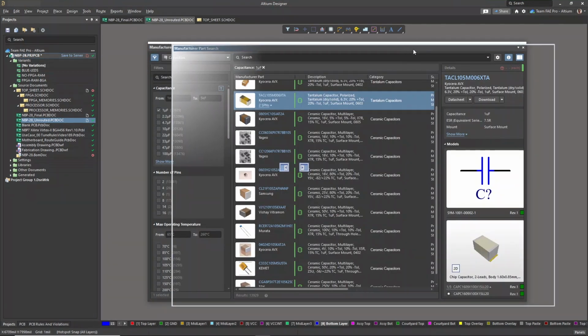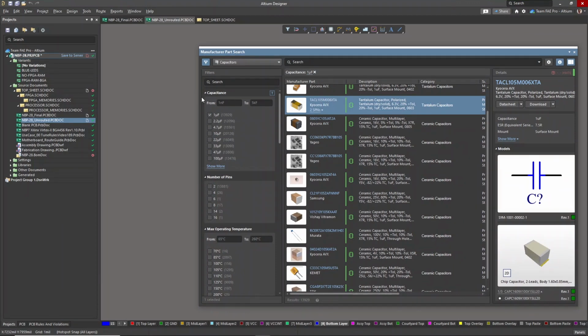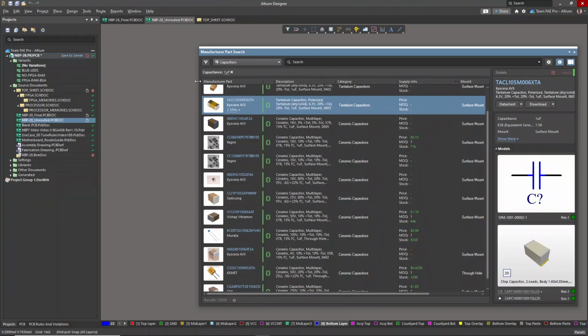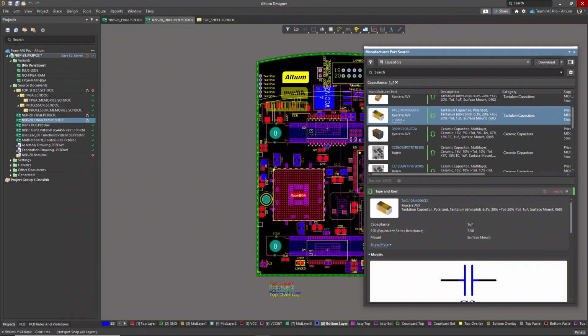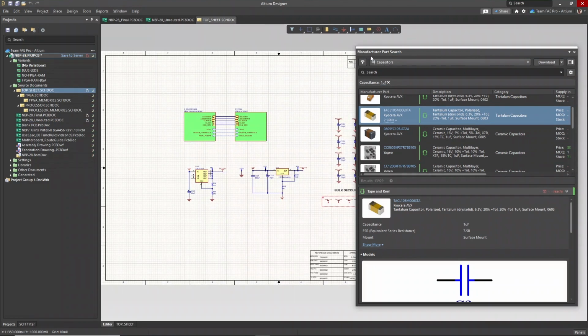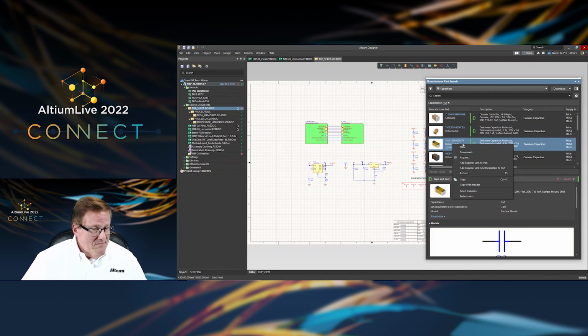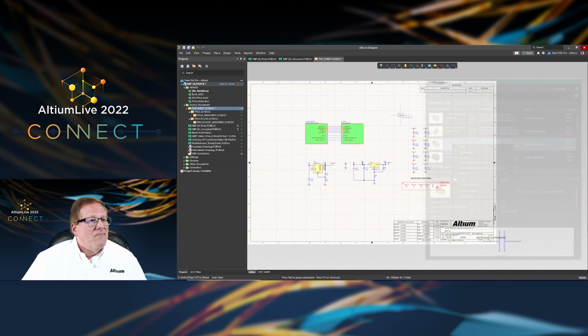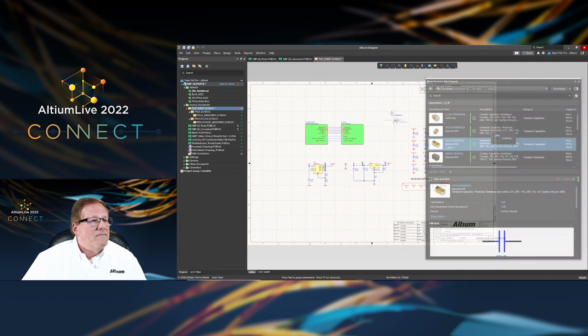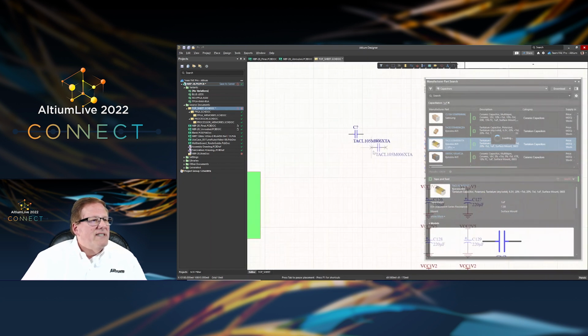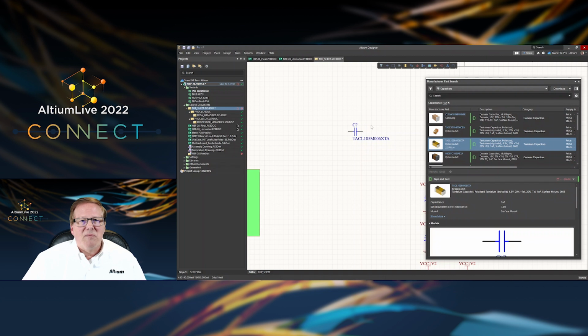So let's see, another really neat thing about this, and it's something that I don't use as much as I should, but it's really nice because when you're at the beginning of researching components, there's just a lot of trade-offs. You might even want to simulate it, but you can literally place right from here. And I go place. And I can actually place this component here, and zoom in on that a little more. So you just place it right from the manufacturer part search panel.